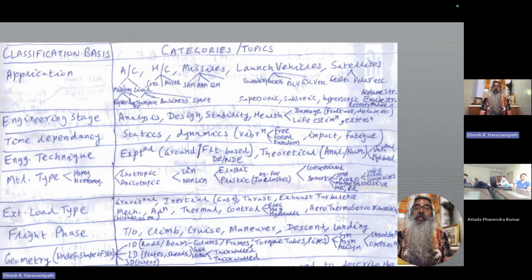So these kinds of possibilities make the analysis slightly more complicated, because you have to take into account not only the stress and the strain, but also how these are getting modified because of the presence of these other physics that is involved. For example, in the piezo, it's electricity, electric fields, which come into play. In the magnetostrictive, it is the magnetic field and the magnetic theory which come into play. So essentially the electromagnetic theory.